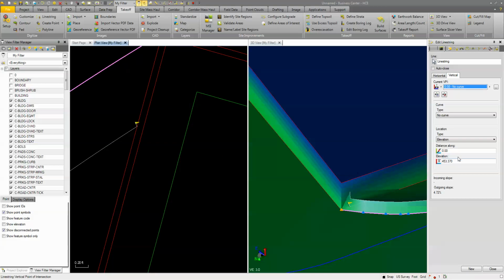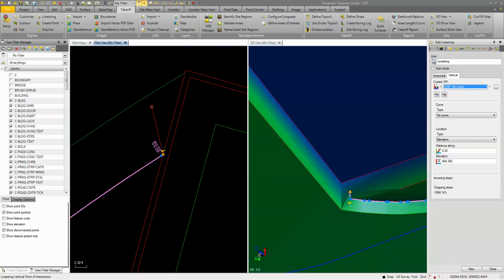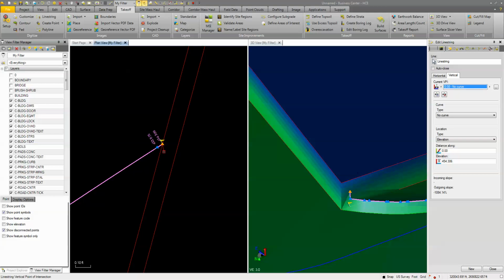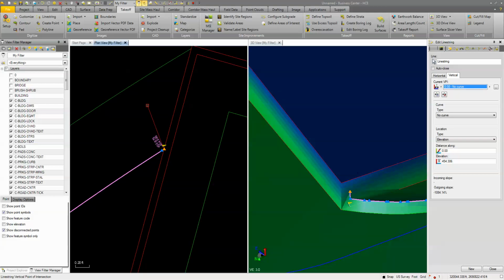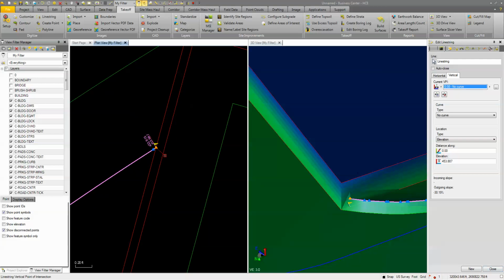We still have this flag over here. What we want to do for this one is set the elevation of these points here so that it's half a foot, or to be honest with you, we could actually just get rid of that point there, but we want to be basically 50% above this curb. So if we use this command, offset slope, and we reference this line, our cross slope is going to be basically 50%, and then the distance would be at this point right here. So it's going to adjust that to make sure that it's the proper elevation from here, right?